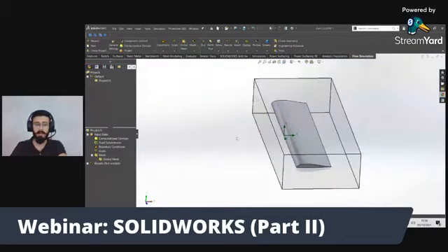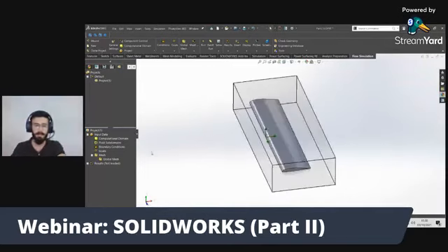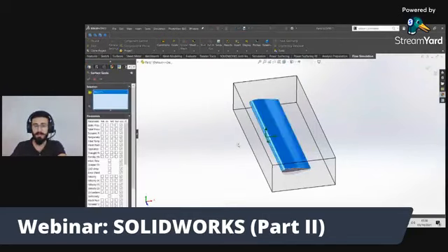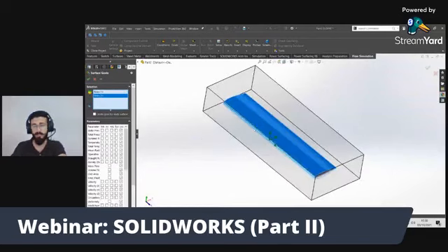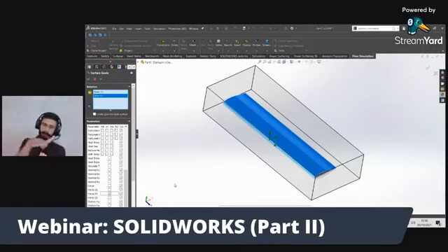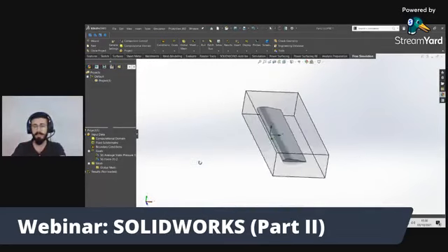This is the domain, where the wind is being blown. This is the domain, there is no big deal with it. And next we will add goals. We are going to add a surface goal. We are working with surface. Surface goal means where you want to see the behavior of wind. And we want to see the static air pressure and force along y-axis. Why do we want to see the force along y-axis? Because when the airplane is moving, there is a push from below, a wind push, which raises our plane. So we will be noticing these two things.